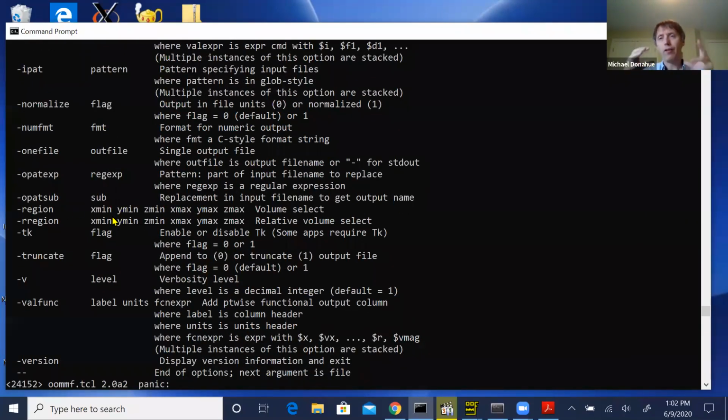So if you don't want to work over the full simulation, you can specify a rectangular subregion, and it will work only on that subregion. And so when I go to do the dispersion study later on, I want to know what the file values are just along a strip in the middle of the full simulation. And so I'll use this program with the region selection to select just that middle, so you can get data for just that portion. Okay.